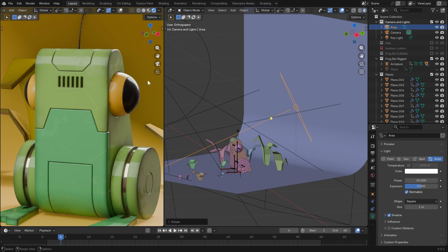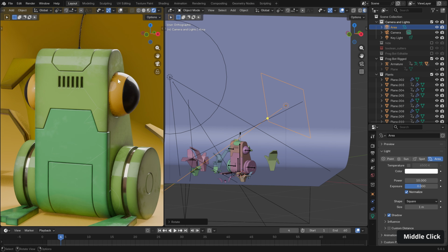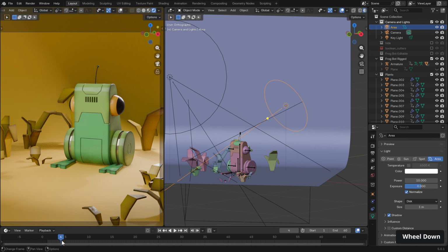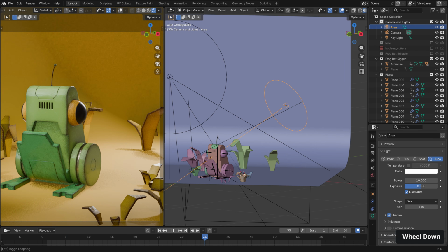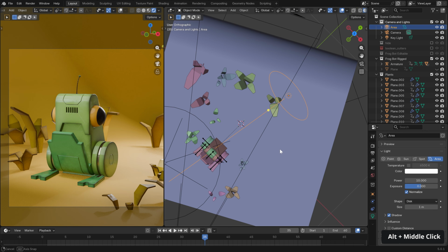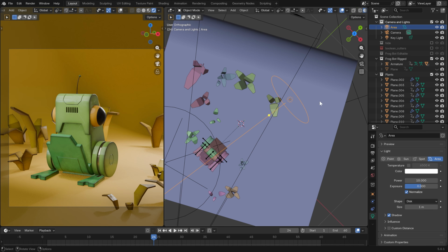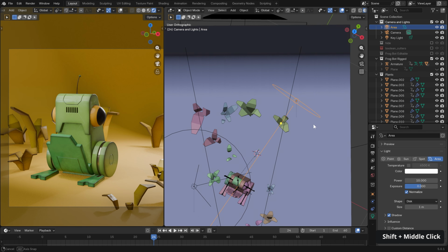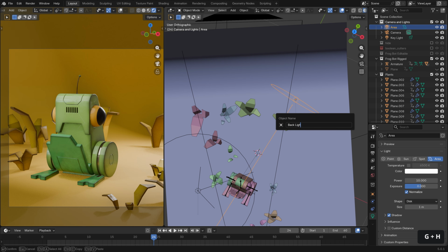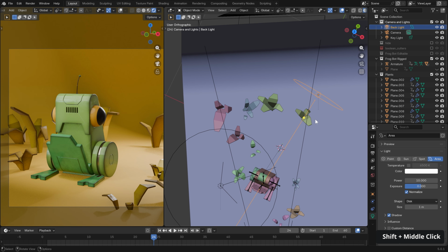The only thing I don't like is the square shape. I feel like a nice circular highlight would be good. Thankfully, we can change this in the lighting options. Shape here from square to disc. Okay, let's see if that continues to work throughout our animation. I might adjust things ever so slightly. I'm just hitting R twice on the keyboard here to go into orbit mode. That feels nice, so let's rename our light here to backlight and move on to the next one.